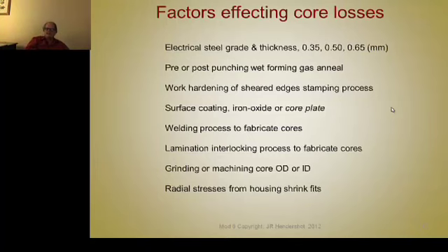Well, it would vary if you had a fixture that you put a big washer on and a big nut that you tightened up, or several screws or threaded fasteners that you had to torque down and tighten to apply the clamping pressure. So it's important that the tooling design, the fixturing, makes that clamping pressure repeatable. These are little tricks that are very important to try to keep your core losses repeatable.